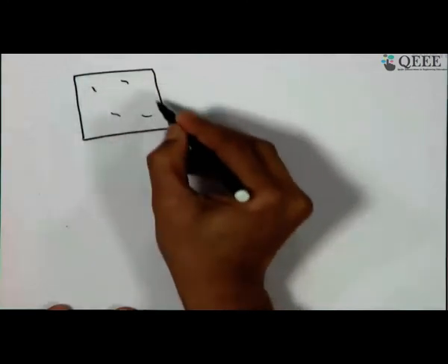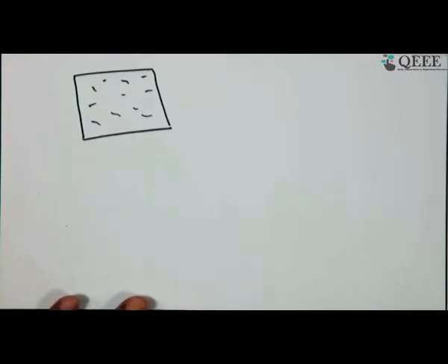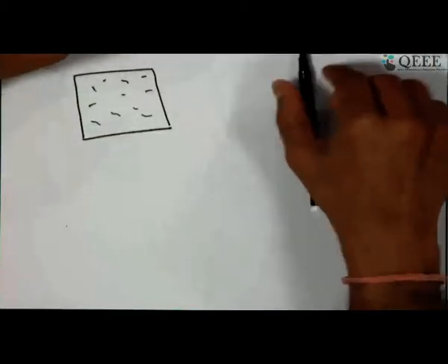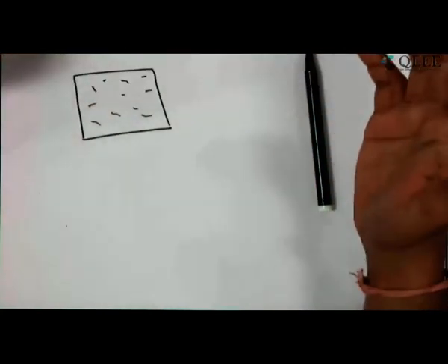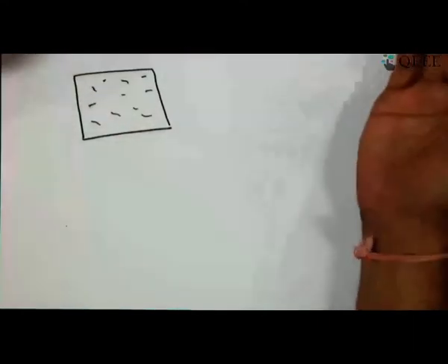You have several flaws in the structure, several small cracks, micro cracks. Now, when your structure is larger, the probability of having a larger number of flaws also increases. So the more flaws you have in a structure, the more prone it is to failure, and the less strength you have. So this is one reason for size effect. Size effect is a separate story. As you say, there is concrete surrounding it. These are all reasons for size effect. But the point is, it is the effect of size that is the reason why we reduce the strength.